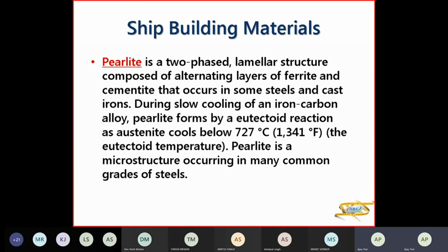We'll be doing different kinds of heat treatment where your cooling is fast, your cooling is slow, and where you're not heating to the eutectoid temperature, maybe heating to half of that temperature. So the various heat treatments we'll be doing will change the molecular structure of the grains of the steel.